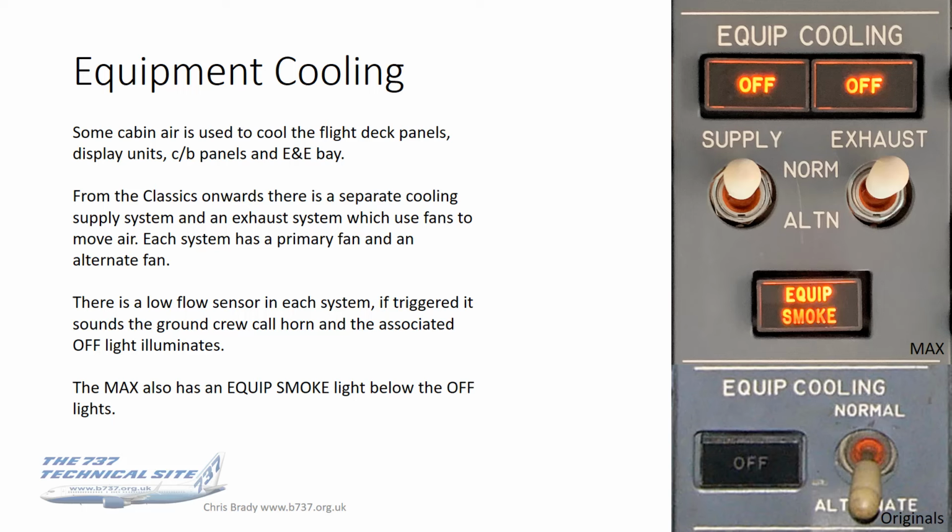There's a low flow sensor in both the supply system and the exhaust system. If that triggers, the associated off light comes on, and it'll sound the ground crew call horn, which you will hear as that sort of distant buzzing in the background in the flight deck.